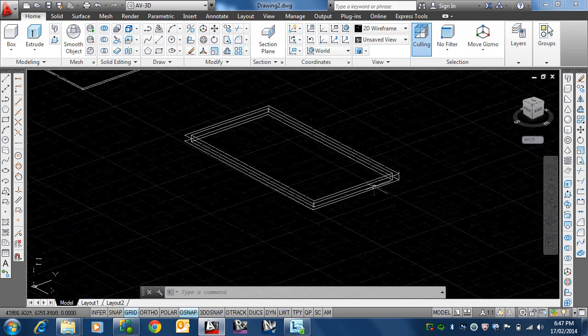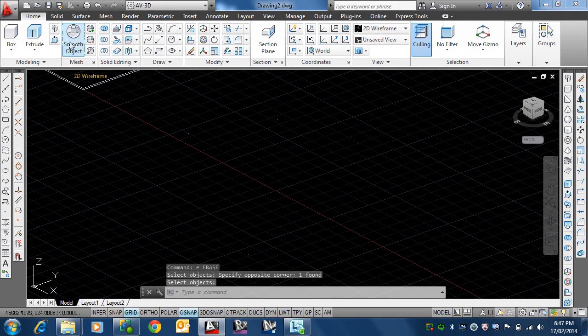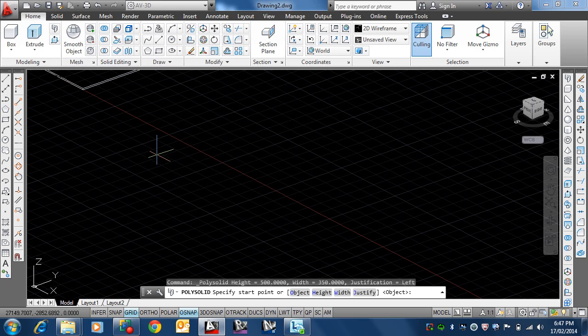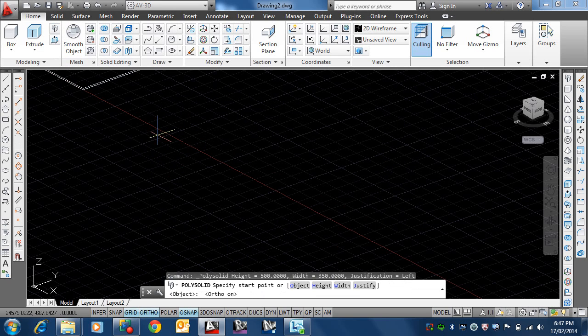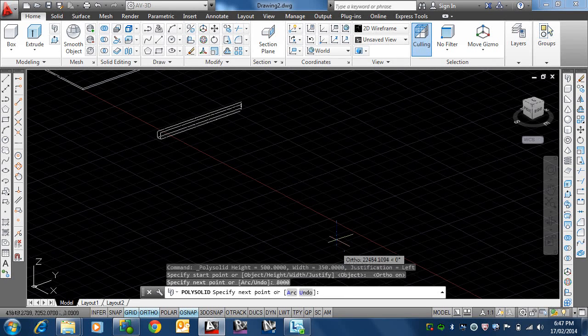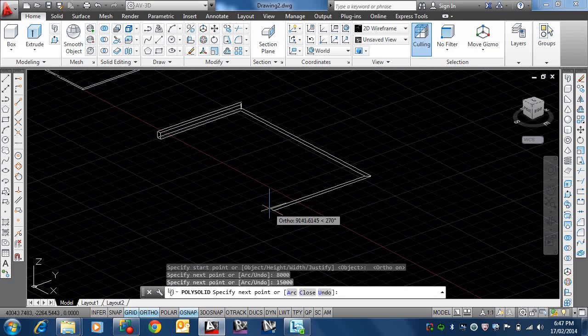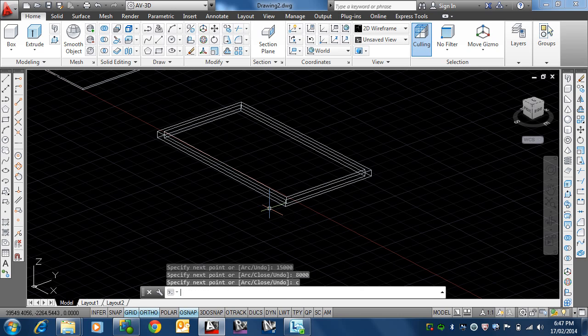You reckon I didn't have my ortho on? Yeah. Let's erase and do it again. All right, so if you go polysolid, I didn't have the ortho on, you're right, I have it on now. But let's go, hopefully that was it, 8,000. We'll go down, and you can do it in wireframe as you can see there. Let's go to 15,000. It's not showing up. Let's go 8,000, and let's go C, enter.